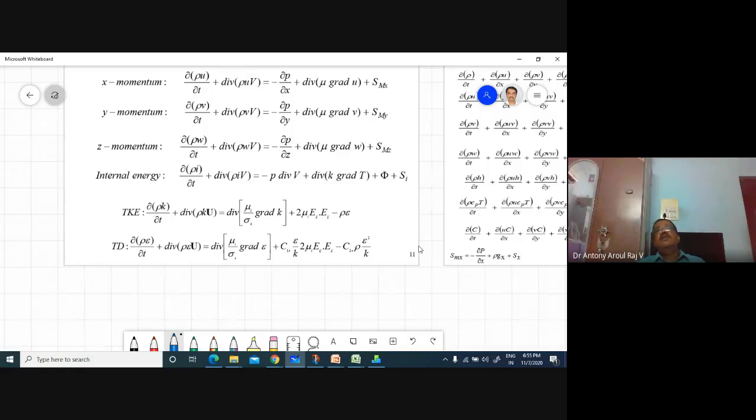So in general, for flow, what do I have to understand? For flow, in general, the properties will be transported. Properties will be transported by two processes. Yesterday we have seen the diffusion process and the convection process. Diffusion means that even if there is no velocity, diffusion will be there. That means it is molecular transport. And if velocity is there, convection will definitely be there. So that is how you have to understand.